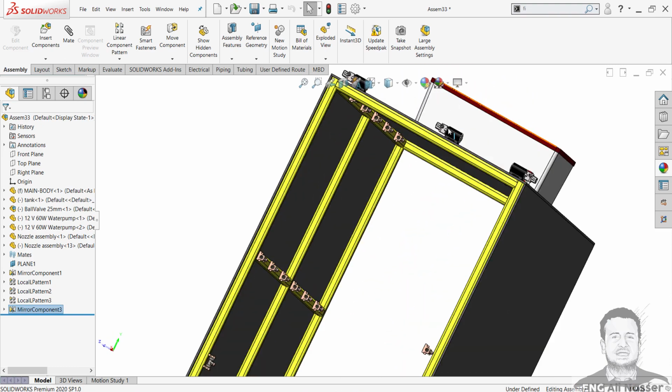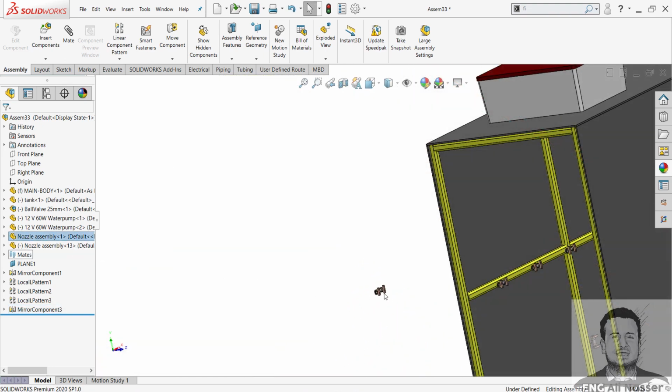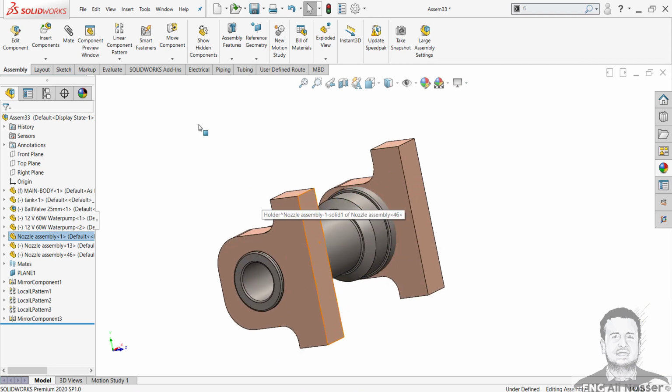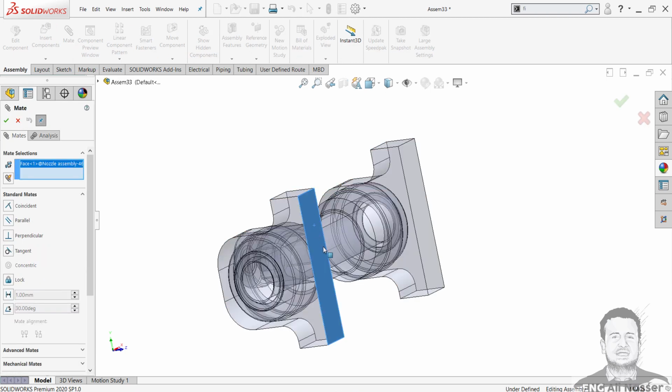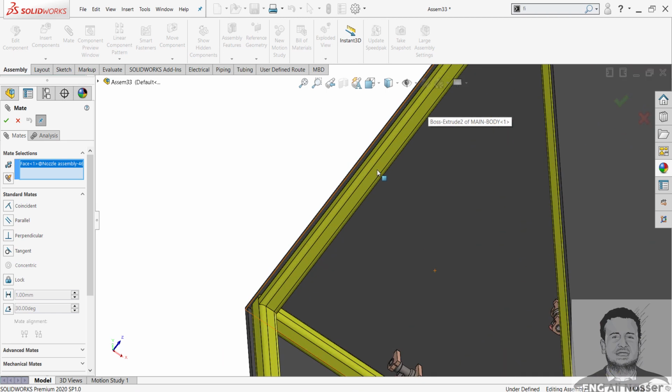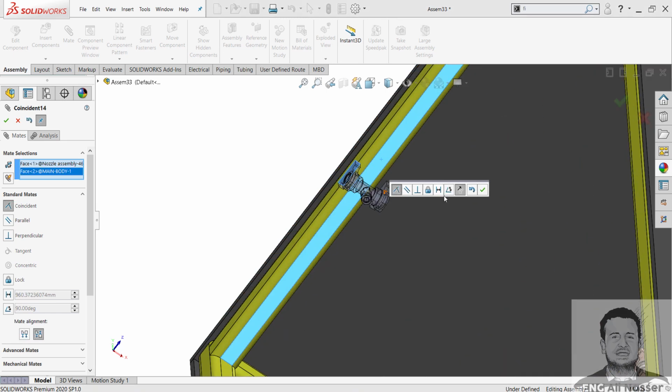Okay, and we will again insert a new nozzle and make some mates. I will select mate and select this face and this face. It will be coincident.